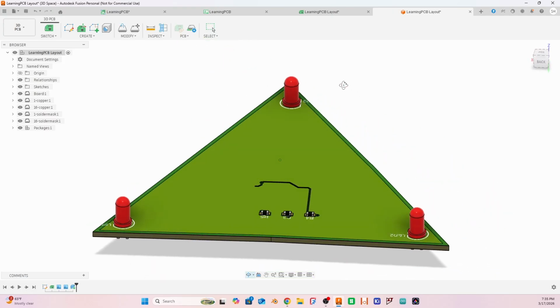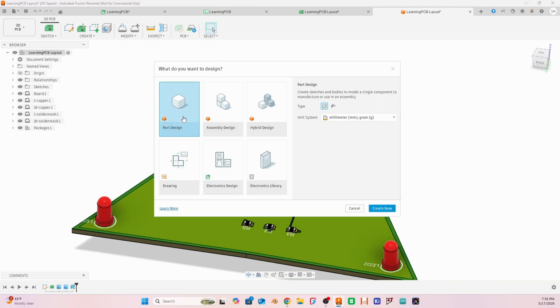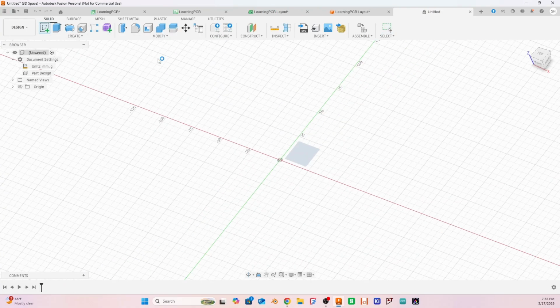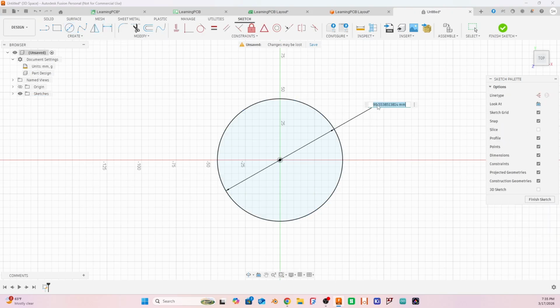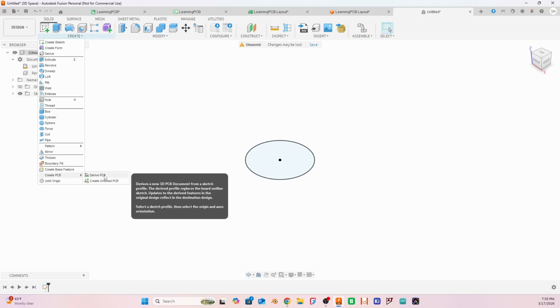That's how you design a profile for your board. First, you need to design a profile, whatever you want. So come over here, design profile. Let's go to sketch. So let's draw, maybe you want some circle, whatever, just do it like that, and then you kind of constrain it, like add some dimension. Let's say we want it to be, I don't know, 50 millimeters diameter, and then click on finish, and this is a profile.